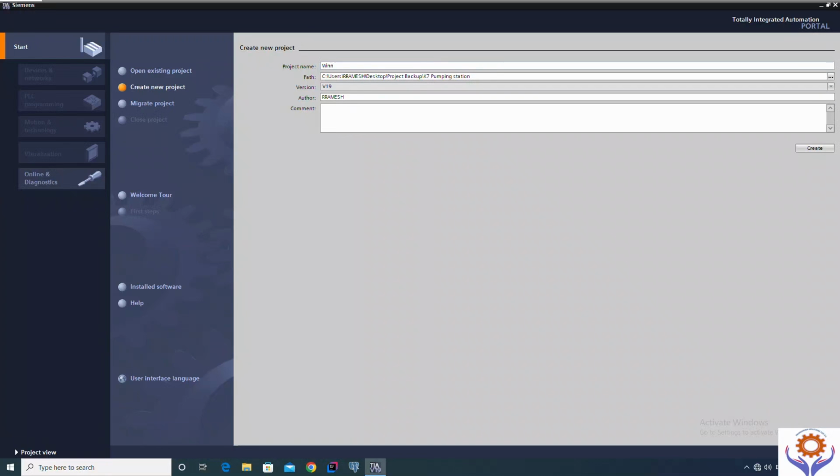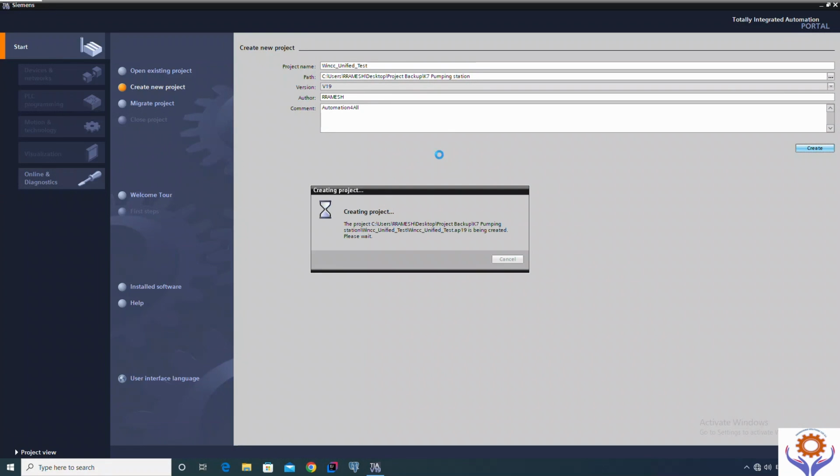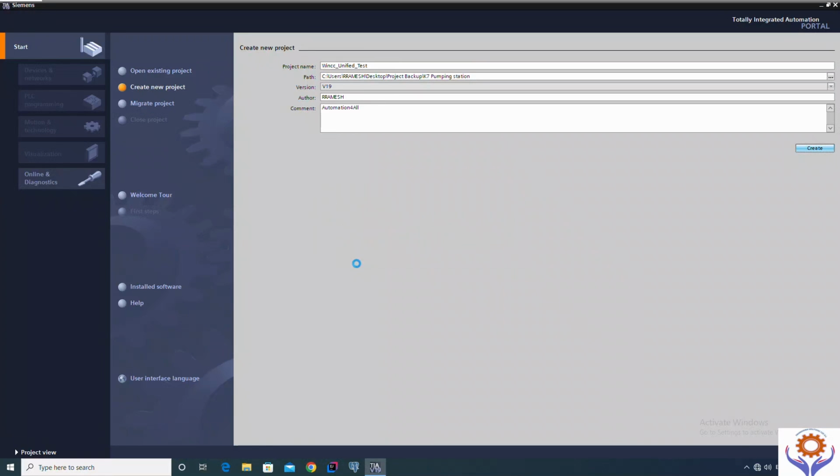Here in the project name, you can provide a new name, called WinCC_unified_test, as per your convenience. And in the comment section, I will provide the name Automation for all. And I will click the Create button. It will take a little bit of time to create a new project. Once it opens the new project, in the new page, you can find the next step.